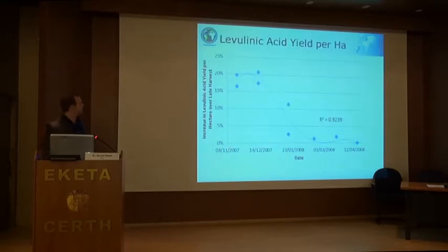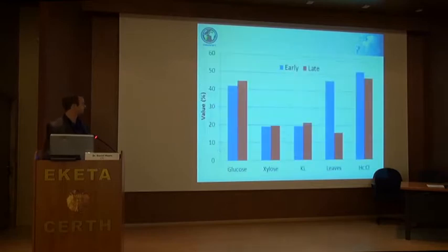So then we use that to plot the linoleic acid yield through the Dibanet process from 1 hectare of biomass. So you're linking the change in standing biomass with the change in composition. And you see the relative advantage of harvesting earlier compared to harvesting this last period. And you can see you can get up to 20% more biofuel or more platform chemicals if you harvest early compared to when you harvest in the latest period.